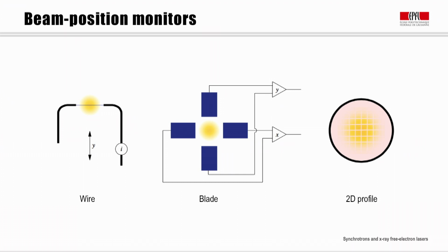Both X and Y coordinates can be simultaneously determined using 4 blades in a configuration as shown here. The beam halo is sufficiently intense to generate a photocurrent in the blades. By moving the four blades together left, right and up, down, the difference in the photocurrent between oppositely facing pairs can be equalized using comparator electronics and the beam position thereby determined.